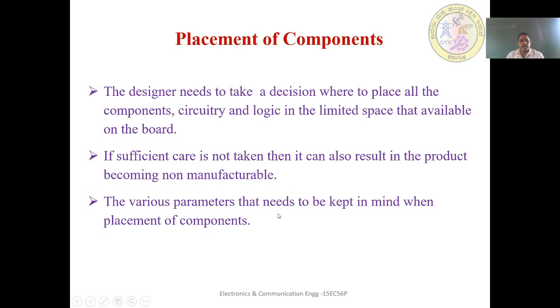The various parameters that need to be kept in mind when placing the components are: connectors, switches, and LEDs should be kept at the edge of the board, and while placing the components, digital components have to be placed far from the sensitive analog components. Digital components are very noisy compared to the analog components. So this is one of the parameters to keep in mind when a PCB designer is designing the PCB.